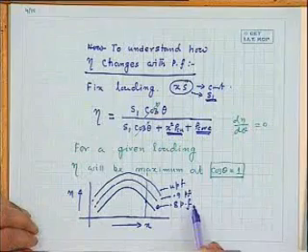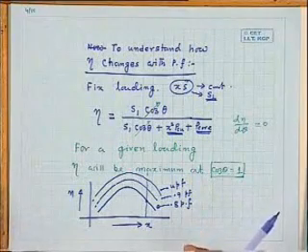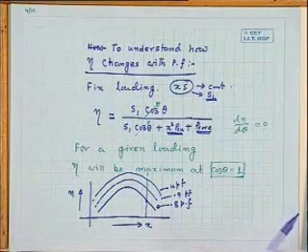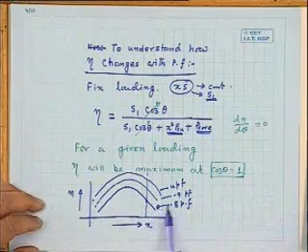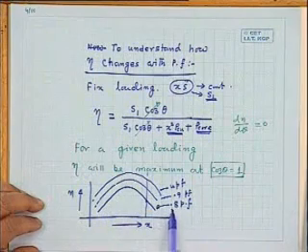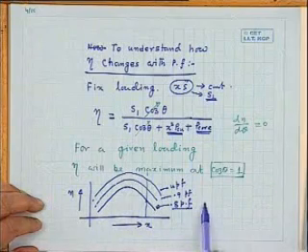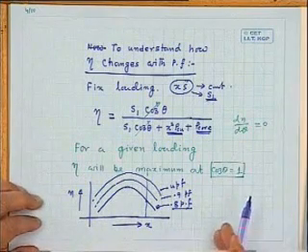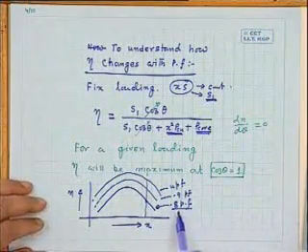Another point I would like to tell at this point, the efficiency does not depend upon whether it is a lagging 0.8 power factor load or leading 0.8 power factor load. For a given curve, should I attach anything like leading, lagging to this power factor parameter? This is not necessary, because this cosine theta takes care of that. It is positive in both the cases. So both for leading 0.8 power factor or lagging 0.8 power factor, it will be the same.